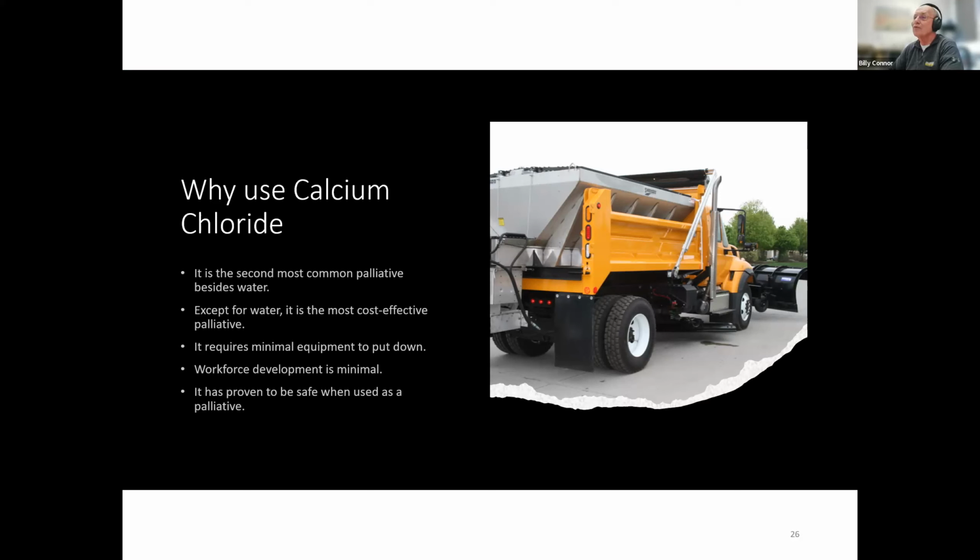Except for water, it is the most cost-effective palliative that we have. DOT is putting it down on the order of $6,000 to $10,000 a mile for a 24-foot top. It requires minimal equipment. We'll talk about different ways of putting that down. Workforce is minimal, and of course, it's been proven safe when used as a palliative.